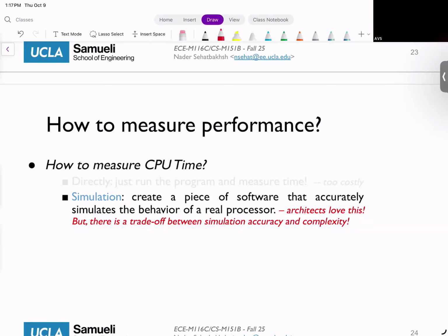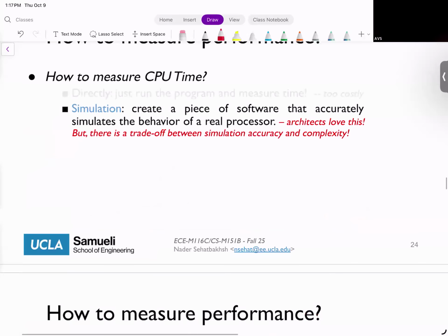But it's a nice thing about simulators that it's quick, right? You can write C code. Changing something in the simulator is just changing a function. Changing something in hardware means 6 months of work of taping things out and so on and so forth. Real products go through all of that: simulation, low-level circuit simulation, lots of verification, taping out, and post-tape out they do lots of tests. That's why it's very expensive to generate a new chip, but these big companies have thousands and thousands of engineers to do that.